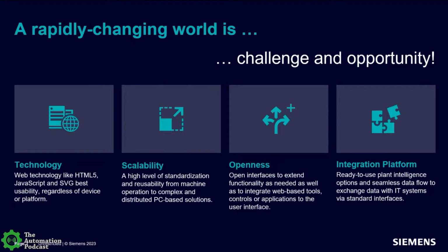There were some key areas that we really honed in to focus on with WinCC Unified. One being in the area of technology, we shifted to be more of a web technology based application. That means that we are more HTML5 driven with JavaScript functionality, the SVG, scalable vector graphics, and we really wanted to make sure that it didn't matter what device you were programming for, core and basic functionality was usable and engineered the same way if it was a Unified Basic Panel, a Unified Comfort Panel, or a Unified PC runtime instance. So all of your engineering and the technologies go across the board very smoothly within Unified Systems now.